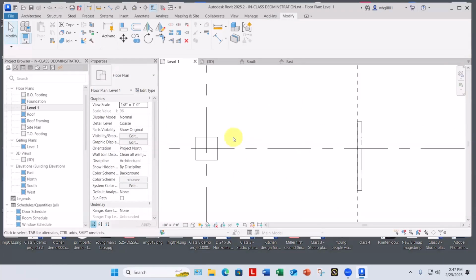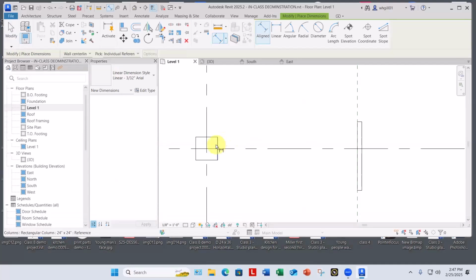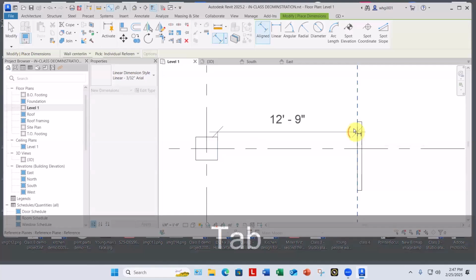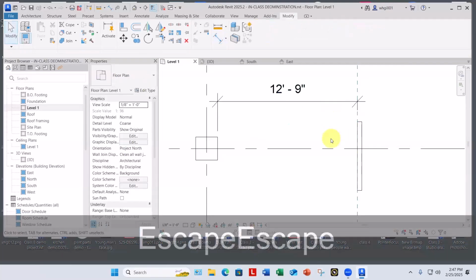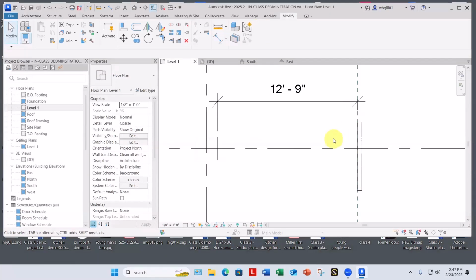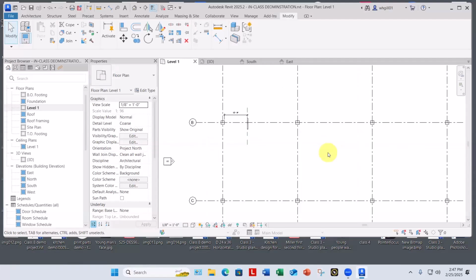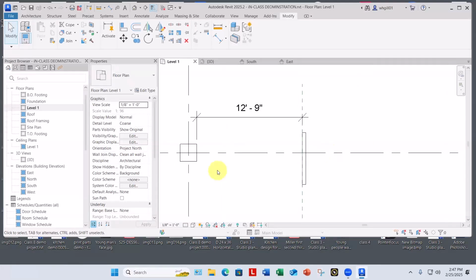So we have this, from this inside edge of this to there. That's what was measured. That's what came back to us. It's not quite perfect yet. What we're trying to find, because all of his buildings work on the center line of walls, is what's the distance from this grid center line to this wall center line. And that's what will actually determine this exactly.